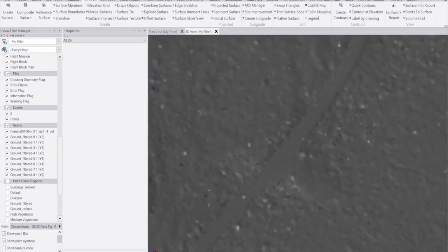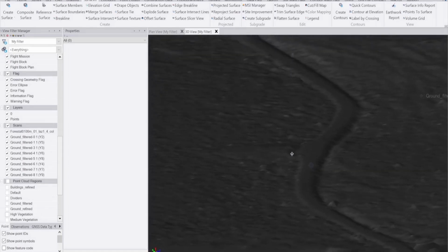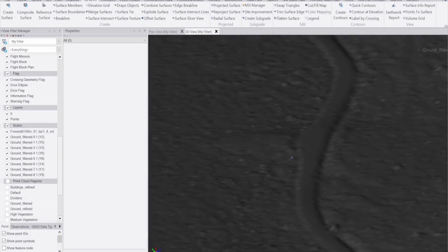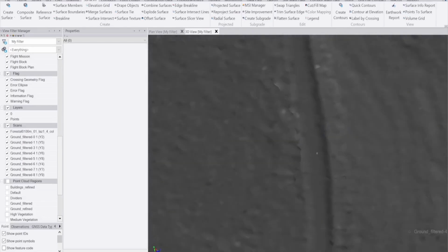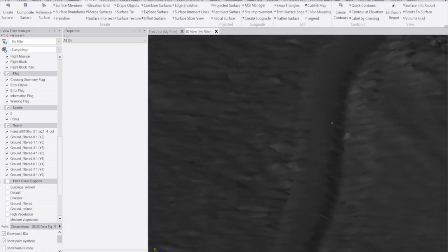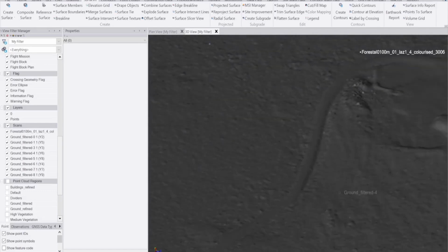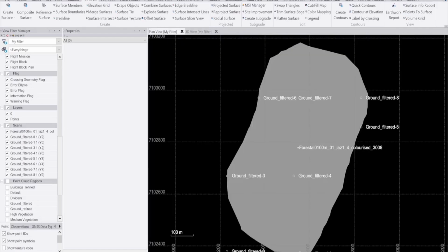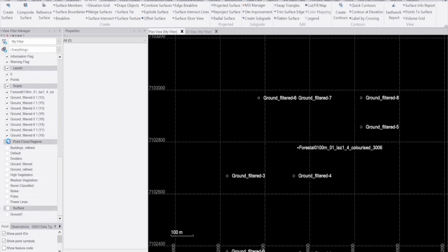And for this particular example, maybe it's not so important, but you could do something similar for curb and channel or other structures that have quite defined features, to make sure that you don't end up with the rounding of surfaces, or rounding of the edges, when you want to have quite a sharp defined surface. So what I'm going to do is draw the centre line of the road.